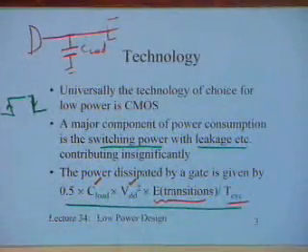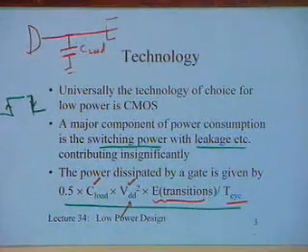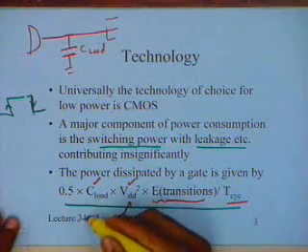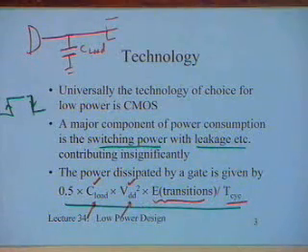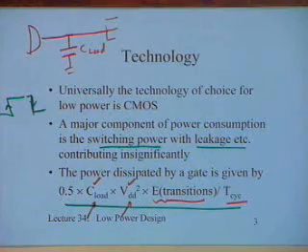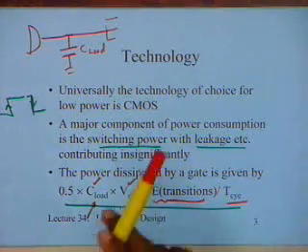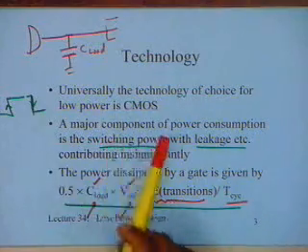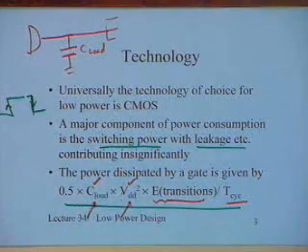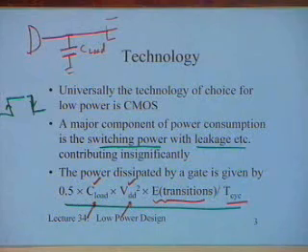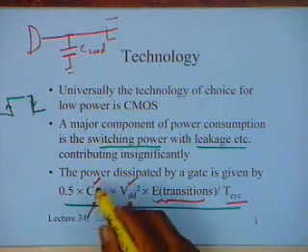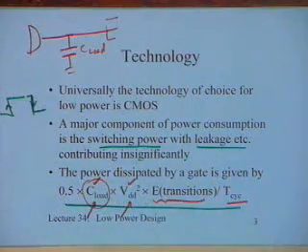If you look at this equation, VDD we know, at what voltage we are operating the chip. C load I can do what is called an RC extraction of the circuit, where I try to extract the capacitance at each of the inputs, and I can find out what the capacitance value is there. Of course, here I need to know the complete layout, because I need to know the length of the interconnects and so on. I need to know the fan out at each point, and I can find the C load.